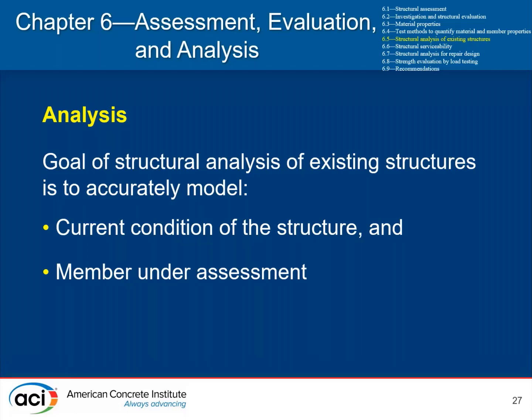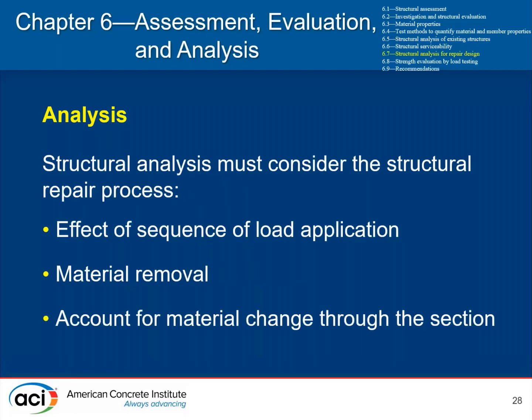However, it's important to understand that the member under assessment can be impactful to other parts of the structure, and so it's necessary to look at the areas that could potentially be impacted by the member that is being evaluated or analyzed. So the structural analysis must consider the effect of sequence of load application, material removal, and it also must account for the material changes through the section.